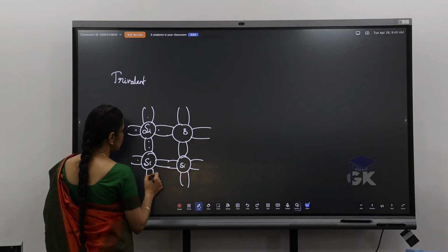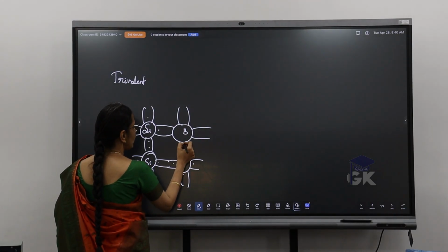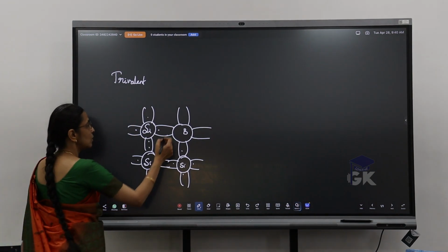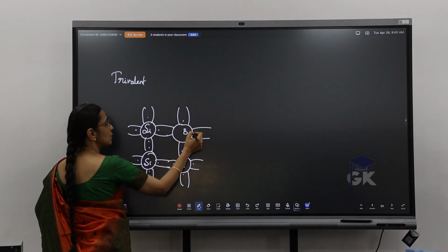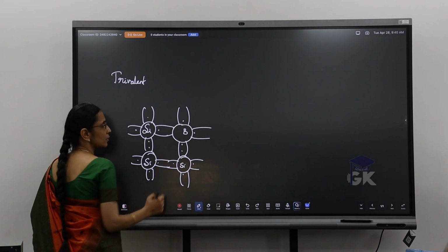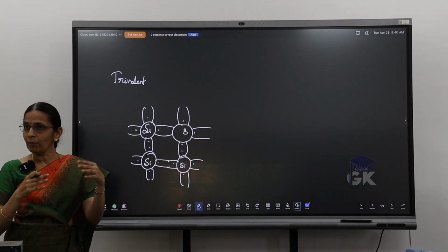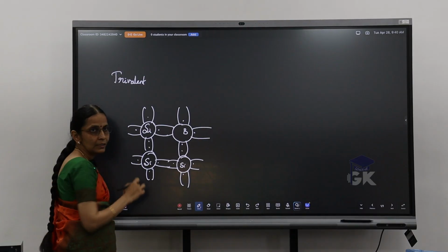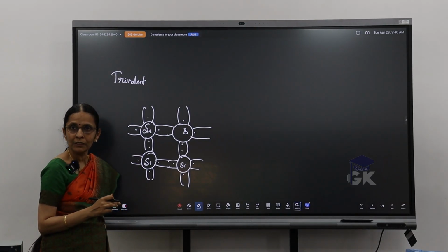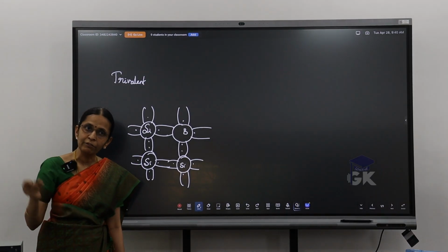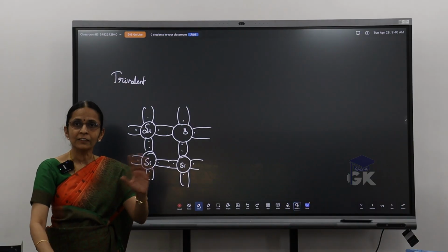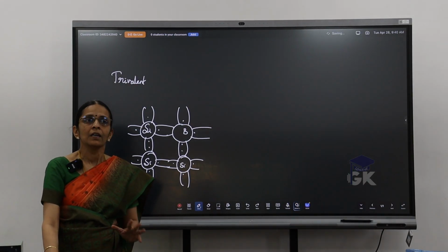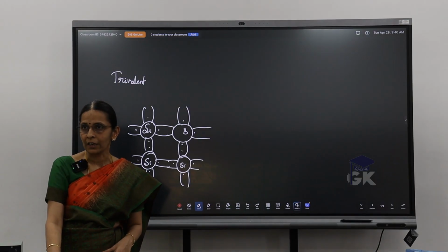So it goes like this. These are your covalent bonds. Boron will have 3 valence electrons, so it has an electron here, here and here. These 3 form the covalent bond with my silicon, whereas I have an empty space here. So what is that empty space? It is a vacancy there which can be filled with an electron.